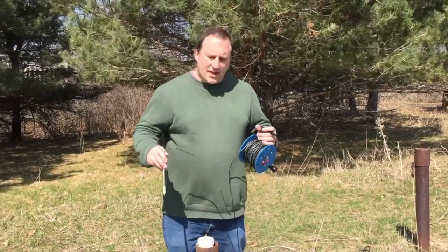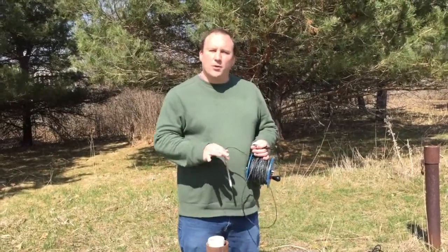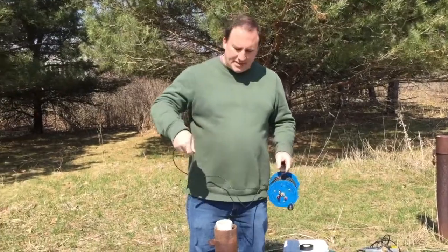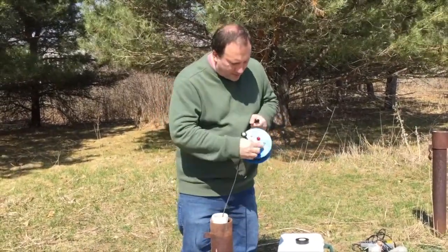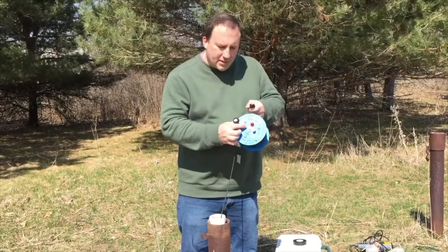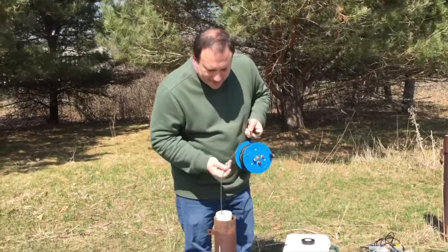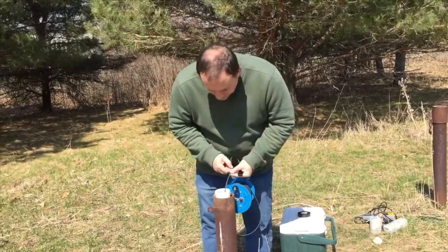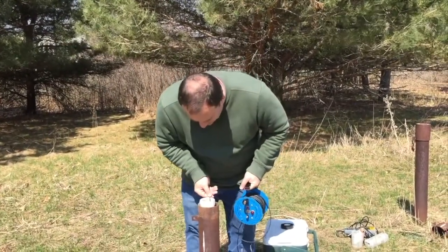Today we're going to do a slug test, and the first thing we need to do before we put anything into the well or pull any water out of the well is you have to measure the static water level. We did this last time. Let's see what it did in the meantime in about a week. So I've got my water level meter. It works. Always test your batteries. So this is monitoring well 2, the deeper one.